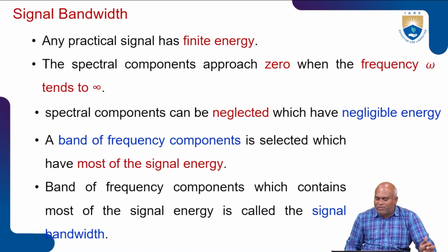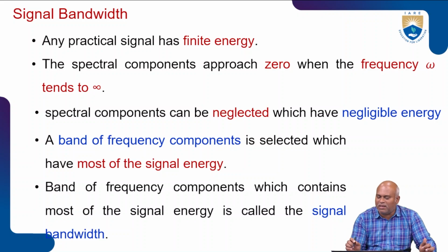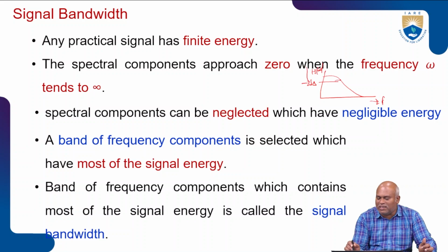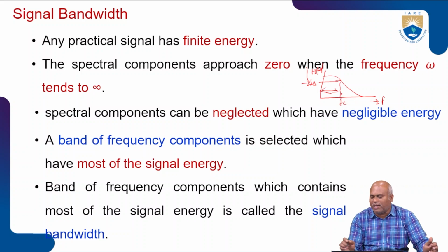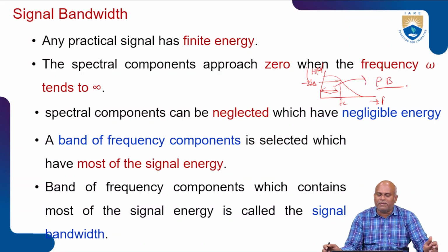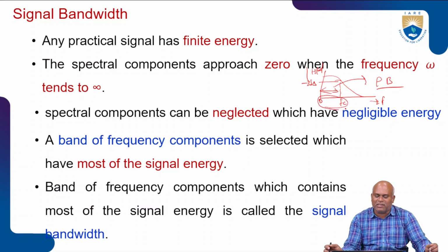Now take the low pass filter. Here the attenuation is minus 3 dB. I represent |H of omega| against frequency. Up to fC it will be represented as the pass band, that is the conduction band. The frequency between 0 to FC is represented as the pass band.